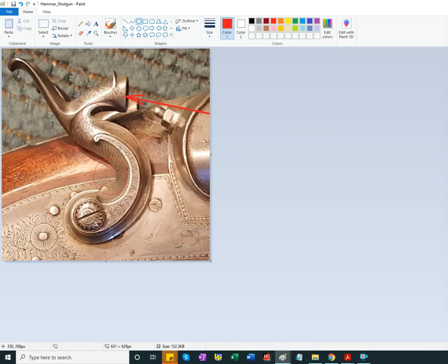It's simply because of the arm of the force. Now, I want to use the line and make it a little bit thicker. So the arm of the moment would be only this much for the same force when evaluating the curved beam stresses in this area, versus this much arm. I tried to make this 90 degrees. So bending stress will be more here than it is here. And it makes sense to make the radius of curvature wider because the stress will be less this way, where the moment is bigger.